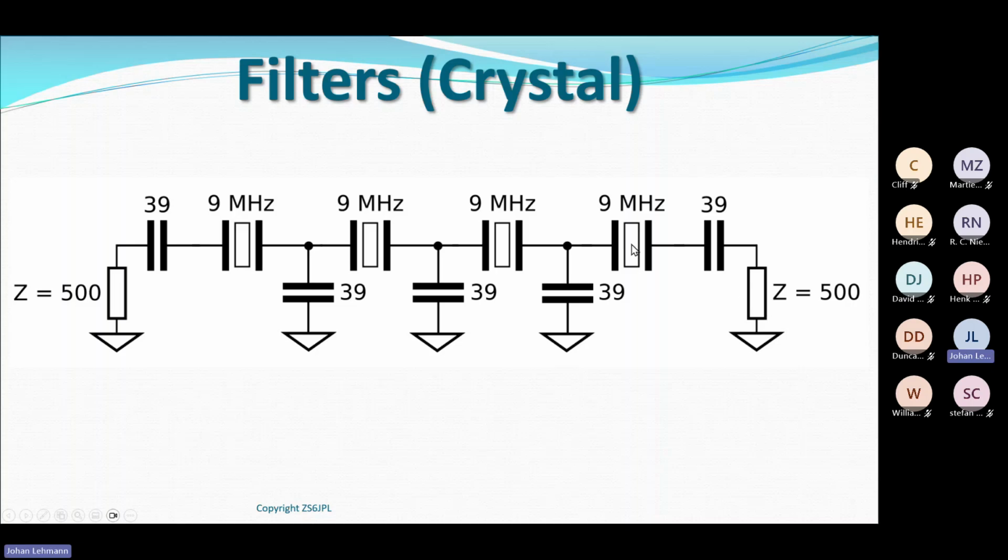Did you do crystals yet? No, you haven't done crystals. Yeah, we did crystals when we did capacitors as well. Remember, the crystal is a quartz crystal which has been cut to mechanically vibrate at a very specific frequency. So it's got an incredibly high Q. Remember, we did Qs when we did tuned circuits. So this thing has a very high Q, and it's made out of quartz crystal which has been cut to frequency and polished to that frequency.